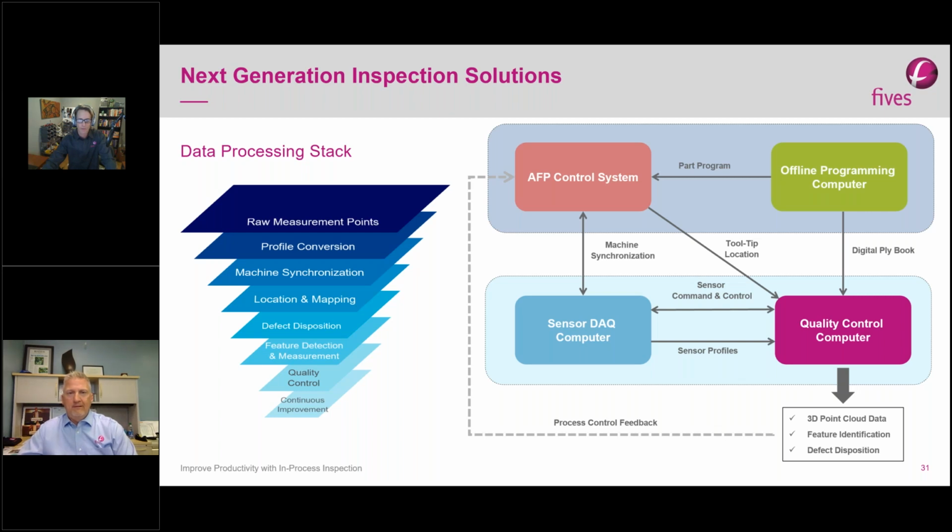We call our offline programming system the Advanced Composite Environment Suite, or ACE for short. ACE has been enabled to produce the key inspection assets required for mapping the as-designed part to the as-measured surface: expected gaps, laps, tow end locations, diverging and converging course info, regional disposition criteria, all the stuff an operator gets from a plybook. So we call it the digital plybook.